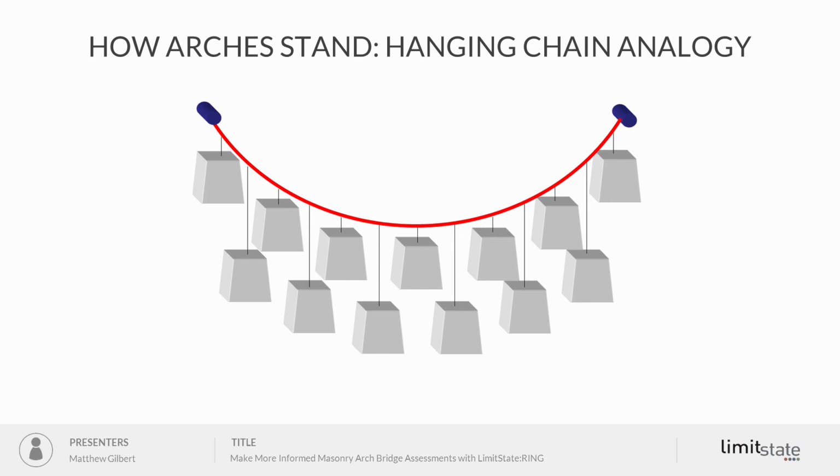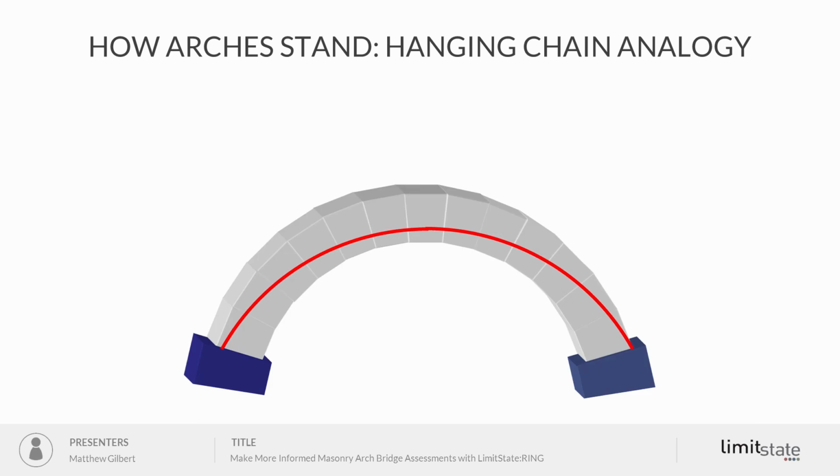If you take all the voussoirs that you're going to use to form your masonry arch, you suspend them from a weightless hanging chain or cable. You look at the profile that chain or cable takes up. You invert that, and you find that you can fit that entirely within the thickness of the masonry. Then you know that your arch should stand when you remove the formwork.